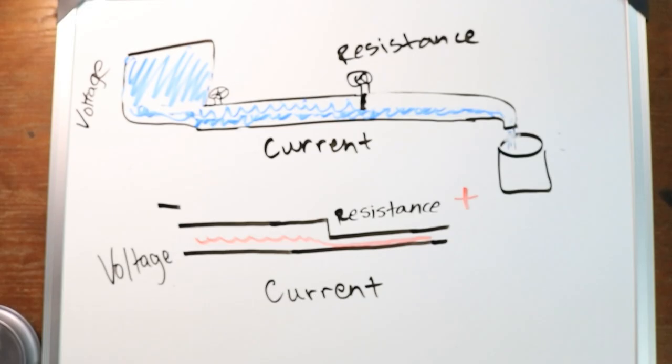If I'm measuring it and it doesn't have 12 volts, then obviously this device is not getting power from somewhere, or the device is not working correctly. Same thing with current. When you have a motor that's pulling 2 amps to work correctly, and then when you're measuring the current, it says, oh well, it's only 1 amp, then you know that device is not pulling correctly and something's wrong in the field.